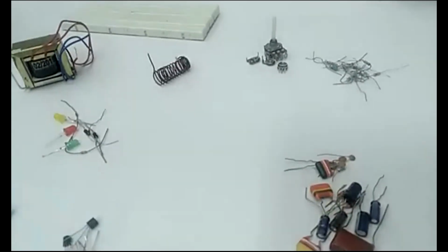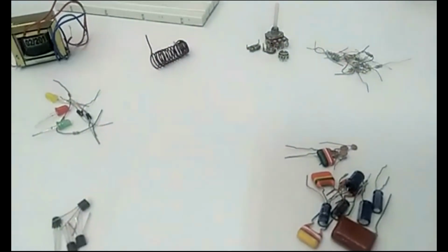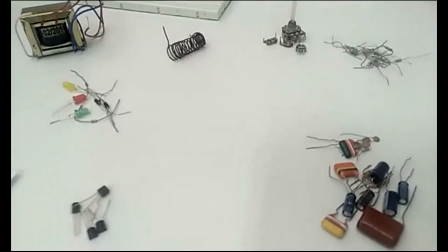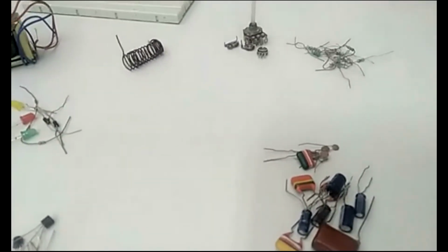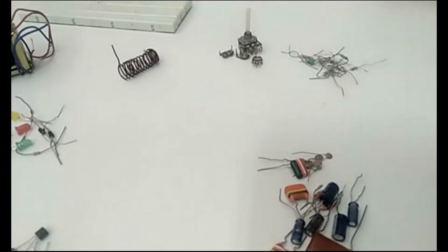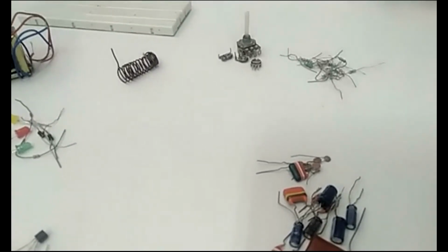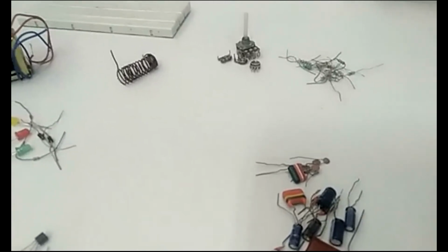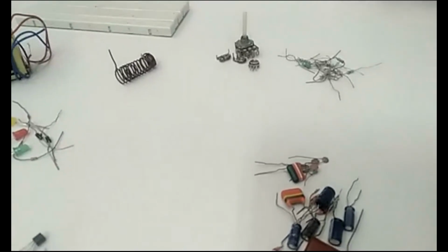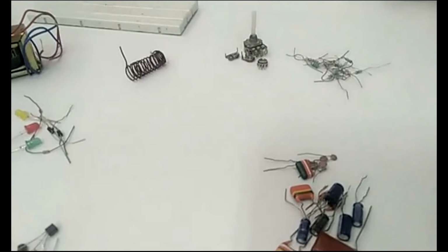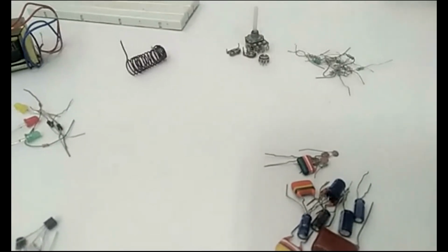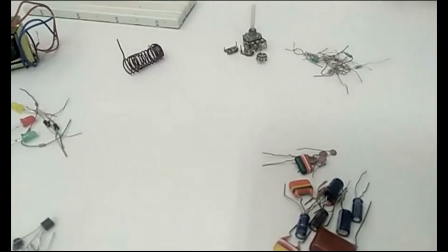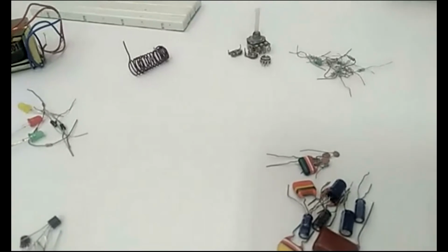There are different types of capacitors here. The first of them, as I told you, is the electrolytic capacitor. How to distinguish an electrolytic capacitor: it has polarity. In broad categories, you have polar capacitors and non-polar, or unipolar, capacitors. Polar means it has a fixed polarity of positive electrode and negative electrode. Electrolytic capacitors are one of those, having a fixed positive electrode and a negative electrode.